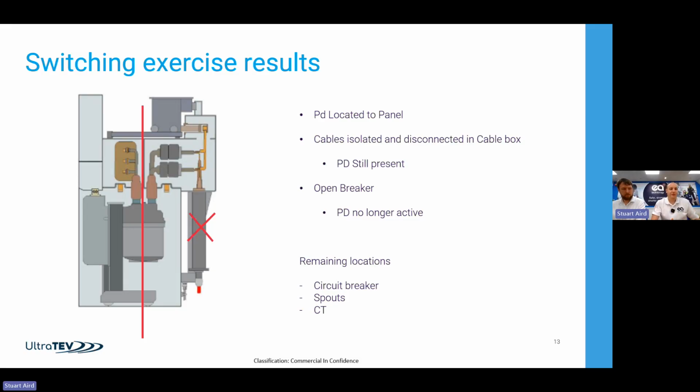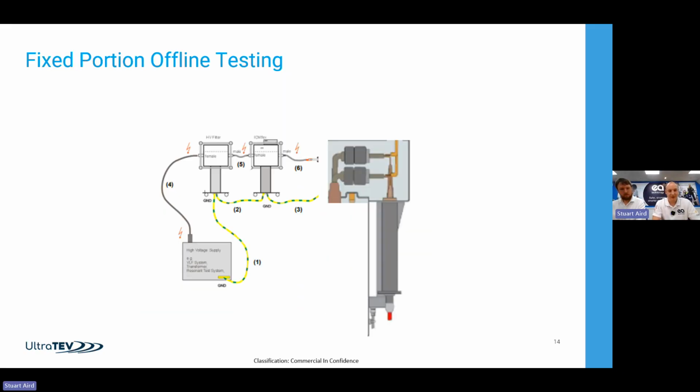After that point, you've got to where you can really with non-intrusive, and the next step is to start doing an offline measurement and energizing each part of the switchgear individually, down to the component level, to determine which of the components may have partial discharge. So the customer actually took a number of measurements and determined that they wanted to narrow this down much more. So we went to site with a 50 hertz power supply. We've got a 50 hertz full frequency power supply, a couple of coupling capacitors, and a smoothing capacitor, and then we can detect.